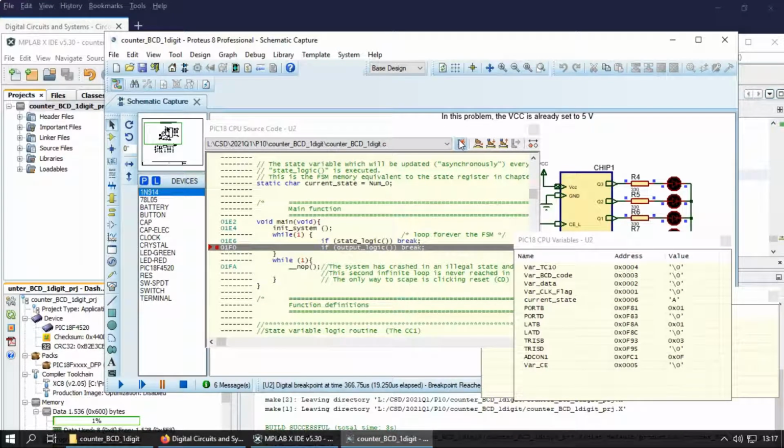So this is the time elapsed. A lot faster. If this is what it takes, 19.25 microseconds, it means that because you have a faster clock, this main loop is executed 52,000 times per second. Well, not bad, but this is a microcontroller, and with a higher frequency for the oscillator you get 19 microseconds. That is okay for many applications probably,